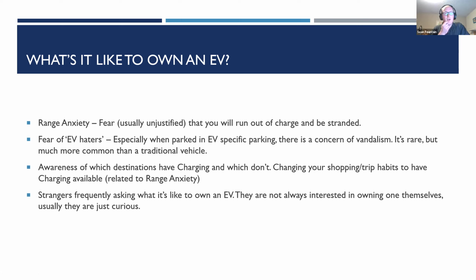I got a question: are there both front wheel and rear wheel drive cars? Yeah. Excepting when you look at the luxury car brands that usually care less about efficiency and more about driver opinion, they'll always be at least front wheel drive. And that's because when you're braking, the weight of the vehicle shifts forward and it presses really hard on the front tires, which means those tires can grip really hard. And so you can brake really hard on the front. And the back wheels, the harder you brake, they have less and less weight pressing on them. So you can't brake very hard without them sliding.